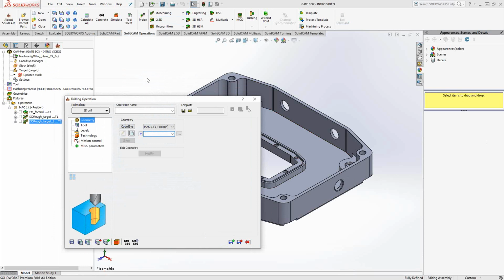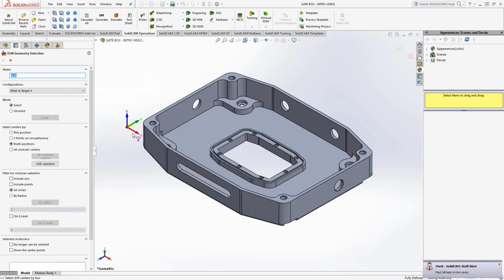The drilling toolpath can be used for any Z direction toolpath. That is spot, drill, tap, ream, pretty much anything you want to just go in the Z direction. And those can be defined by points. So let's go to New Geometry to define our points.